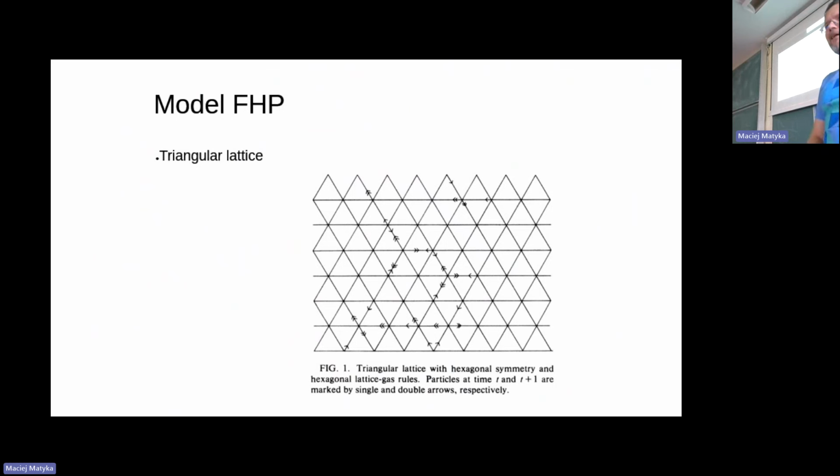And by changing the set of collisions, you can, for instance, change the viscosity of the system. So if you want to numerically simulate a fluid, you have to take another set of collisions, because the collisions can be treated in different ways. For instance, you can take only binary collisions. As in the HPP, we had only one collision with two particles. If there were three particles approaching one side, nothing would happen. They would just go like that. There would be no change.